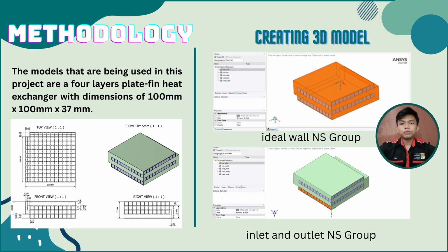Okay, next we will move to the methodology. The model used in this project is a 4-layer plate fin heat exchanger with dimensions of 100mm length, 100mm width and 37mm height, which is a small portion of the benchmark model we referred to, with dimensions of 1000mm length, 1000mm width and 1523mm height. Both dimensions do not include the cross-sectional length of the channel.